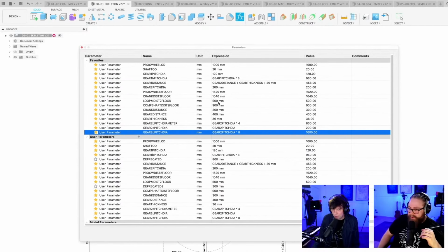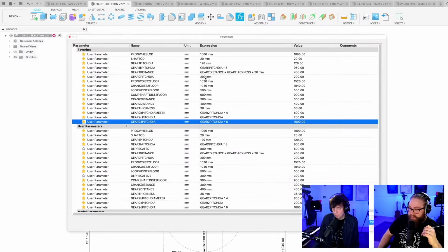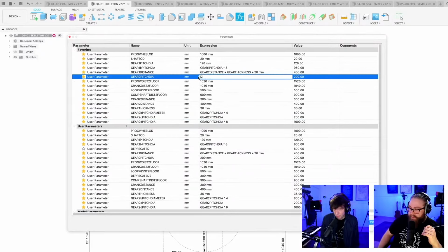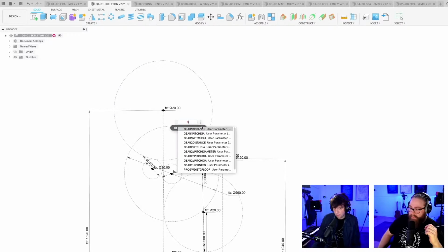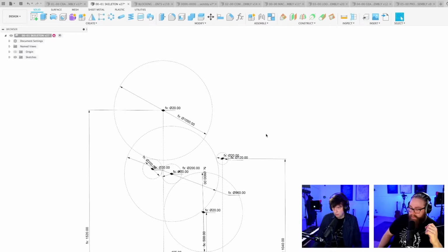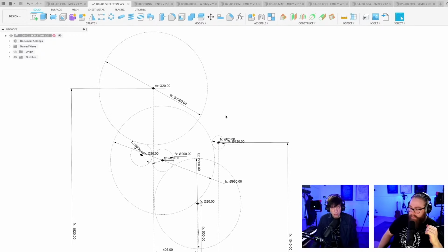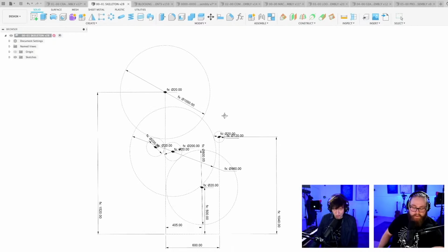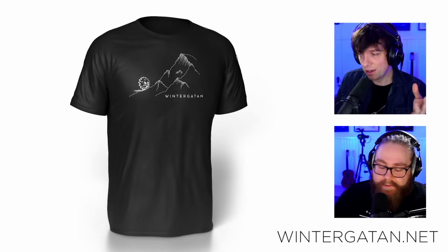I'm going to change gear 2. I'm gonna do 120 on that one as well. And then things... should be 960. This looks much better. And this is gear 2D pitch dia. Okay. I'm running late to my appointment. It worked. And we have learned so far so good. Fusion 360 is doing well with the global parameters.